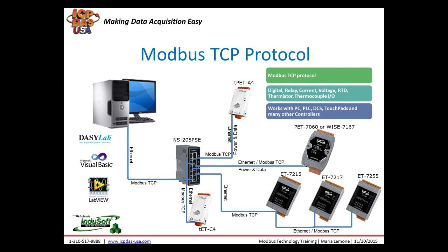Modbus TCP Protocol is a variant of Modbus Protocol that was developed in 1999 to allow Internet and Ethernet-based access of Modbus devices. Modbus TCP-based equipment communicates over Ethernet cabling. Many buildings have Ethernet cabling installed, so adding Modbus TCP devices is very convenient. Modbus TCP Ethernet cabling supports communication distances up to 100 meters or 328 feet.